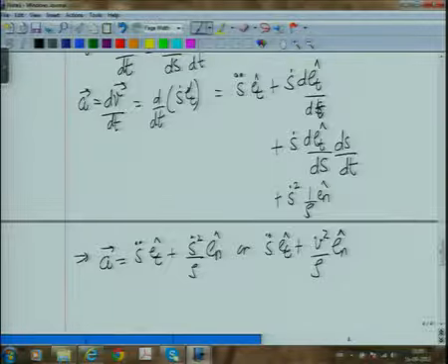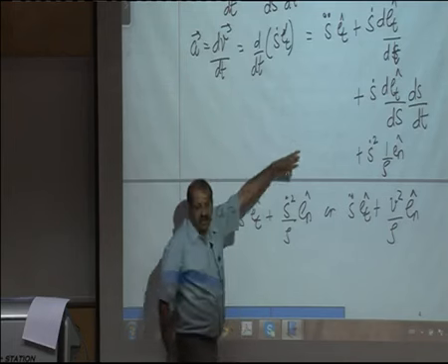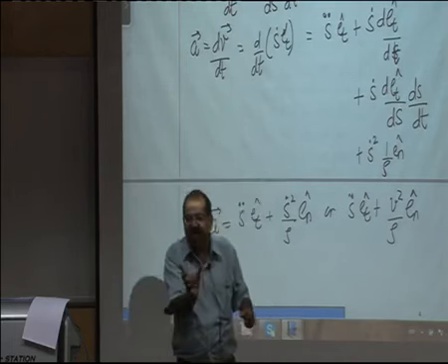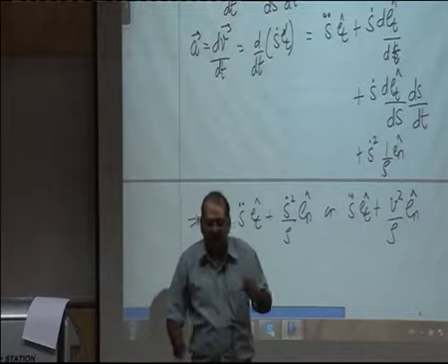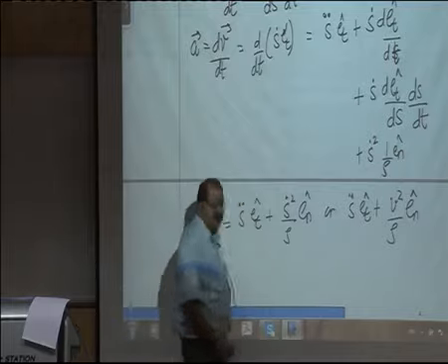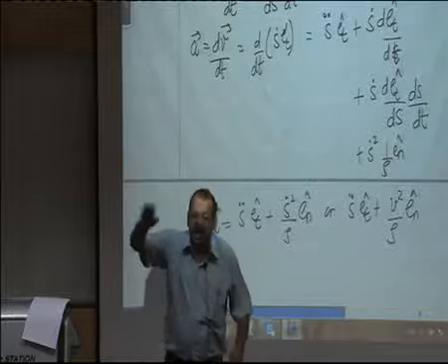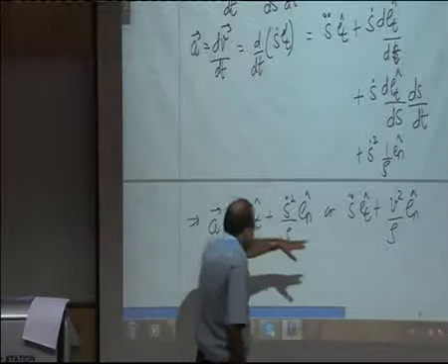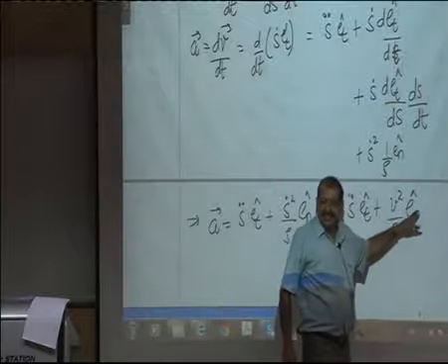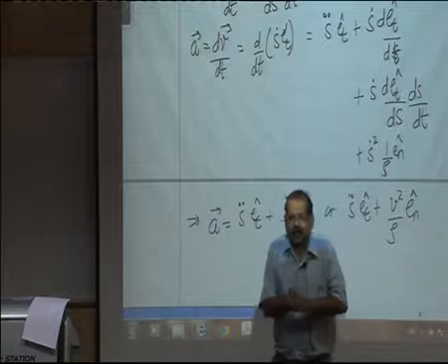If we look at things in a circular path, and we place the origin at the center, then what do we know? The velocity is r omega, in the tangential direction. So, that is equal to s dot. s is r theta, so you take its derivative, r is constant, so you get r theta dot, which is r omega. And acceleration has two components: one is r alpha and the other is minus r theta dot square, and E n actually is minus of E r if you place things at the center.